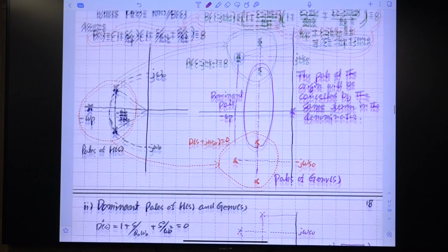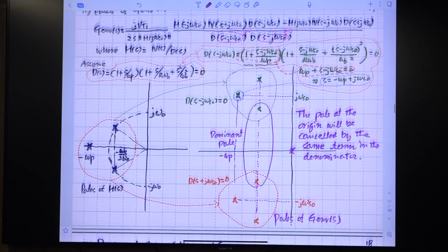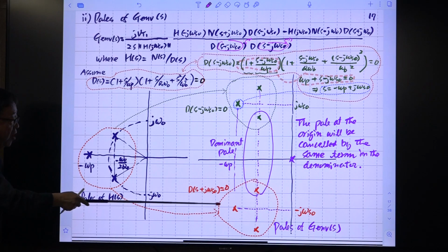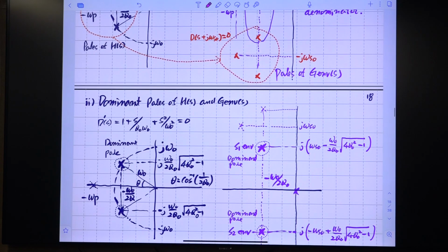Let me explain once more. All right. So this is the denominator of H(s), the tank transfer function. Originally we had an additional first order term here. We forget about this term because it translates into 2 separate poles, which are not dominant poles. We are only considering the dominant poles. So just consider this part and this part. It's denoted as D'(s). We are only interested in this term.